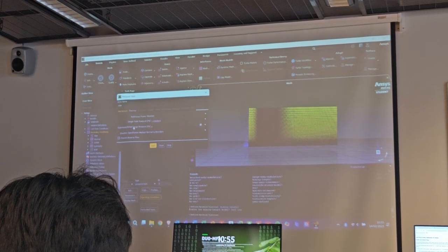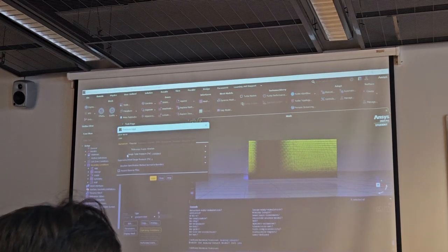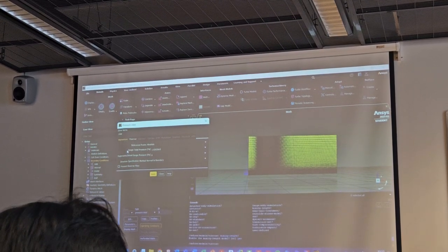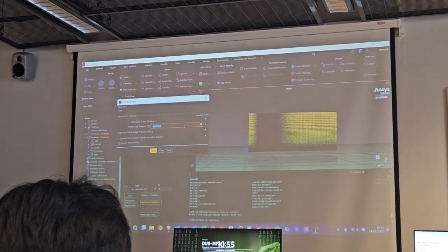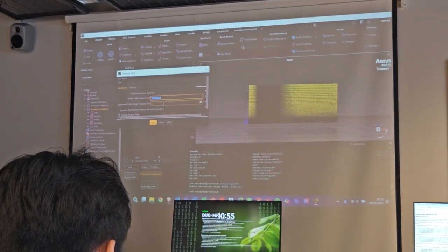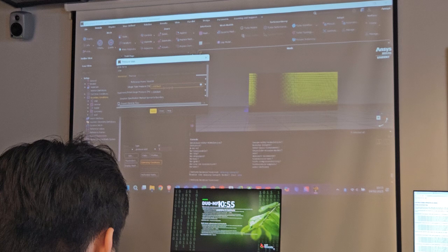Then there is the supersonic initial gauge pressure. That's not a real boundary condition, but an initial value that you want to set there. It's good practice, if you don't already know the dynamic pressure or the flow velocity there, to set it to the same value as the gauge total pressure.